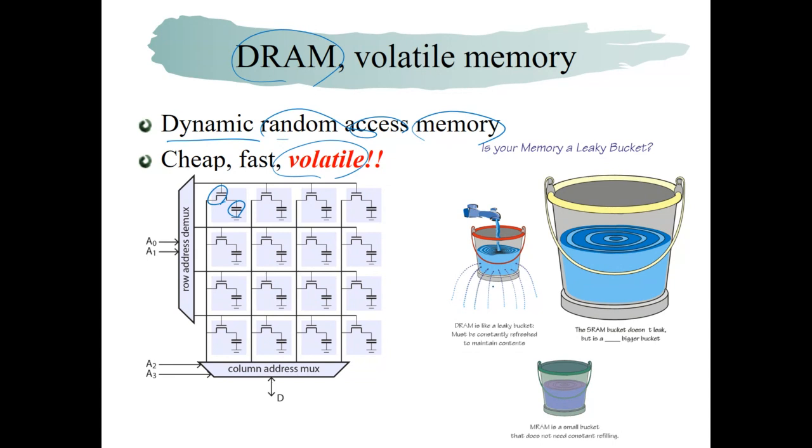So here is a comparison. If you store water in a basket, but this basket has many holes, DRAM has some leakage of water, or leakage current. So the stored water will disappear eventually. That's the very important weak point of DRAM. And in another kind of RAM called SRAM, there are no holes, so you can store the information, but it's very big.